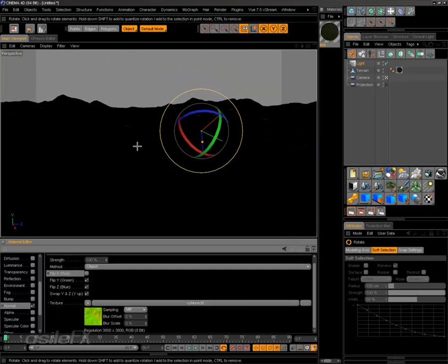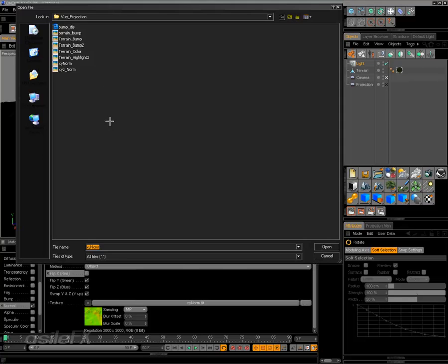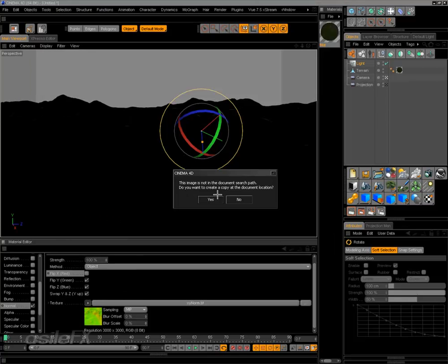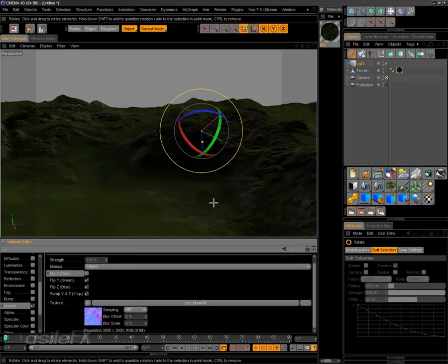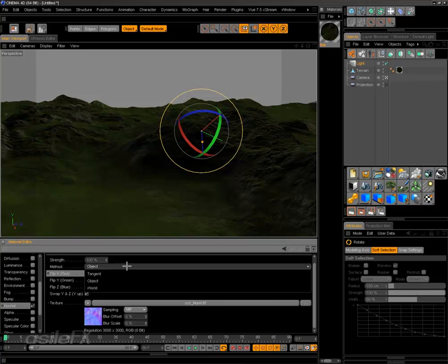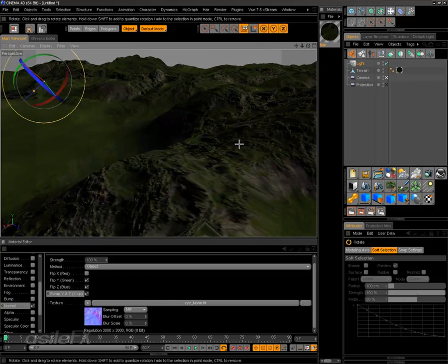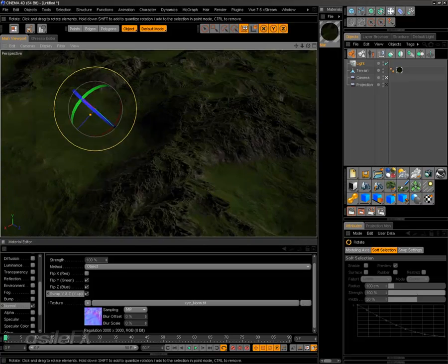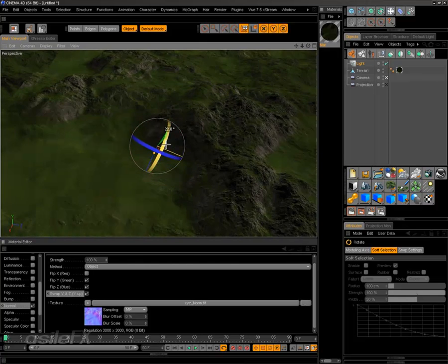And it does look like in this case, because of the original direction of the camera, not really having enough depth, I am going to need to use the XYZ normal. So we'll go ahead and load that in. And what I have set up, still the object mode, I'm flipping the Y, the Z, and then swapping the Y and the Z. So now we have a correct lighting setup. We can adjust the lights however we want.